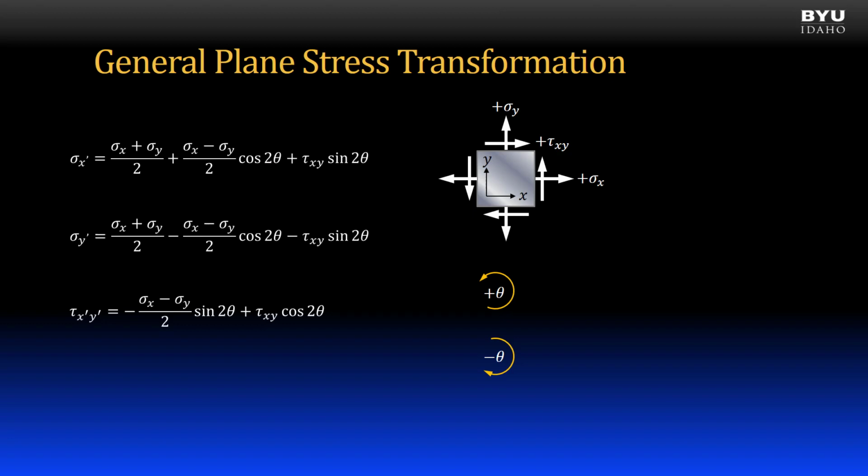The 3 input stresses represent the state of stress on a given plane stress element at some orientation defined by x and y axes. The typical sign convention is that for normal stresses, tension is positive and compression is negative. The normal stresses are shown as positive on the stress element shown. For shear stress, tau xy is considered positive in the orientation shown on the stress element.